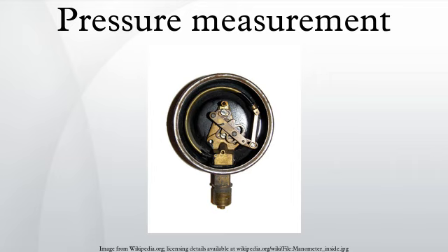When measuring liquid pressure, a loop filled with gas or a light fluid can isolate the liquids to prevent them from mixing, but this can be unnecessary, for example when mercury is used as the manometer fluid to measure differential pressure of a fluid such as water.